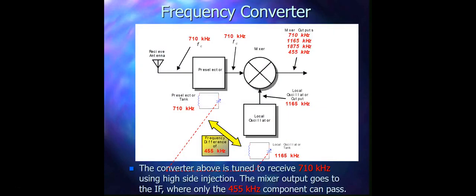So now in this example, you see a frequency converter, and then you have a preselector, mixer, and a local oscillator. From here we are sending a 10 kilohertz carrier frequency signal to the mixer, and we know that at the output we will have 4 different frequencies based on the local oscillator frequency we are sending through this.